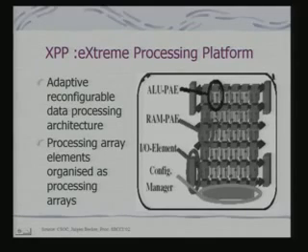Each ALU has got its own RAM, and it has got a set of IO elements, and you have got a configuration manager where you put in the code to say how these ALUs will be configured for a particular computation task, and the data for those ALUs will be in this RAM. So you can see the extent of reconfigurability that you have got now, and you are using a processor core and you are reconfiguring the hardware depending on the application.